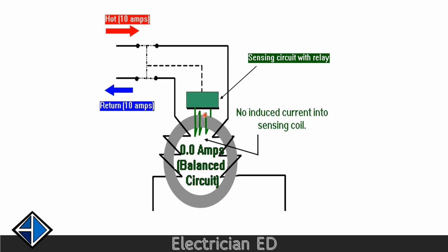This other coil here is a sensing circuit. It would be like the secondary coil on a transformer. And the circuit will detect any voltage here that's created if there's an imbalance in the magnetic field here. That will in turn trip the relay, which will open the contacts and stop the current flow immediately, instantly. So anything that happened down here that was imbalanced will not continue.